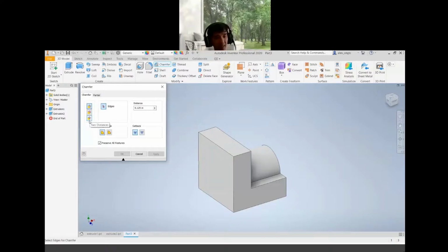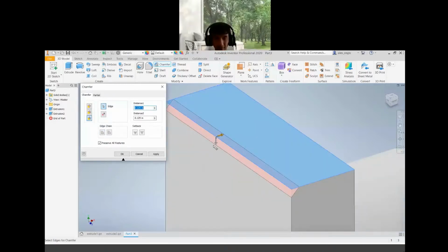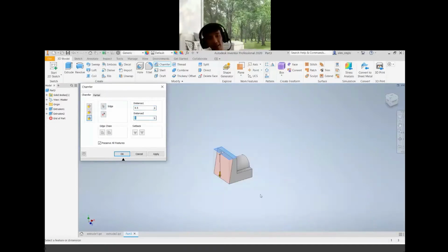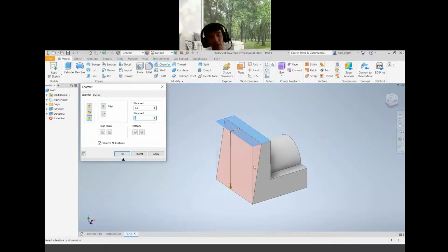Now they will ask you, status bar. Again, please refer to the status bar. Select center of circle. So it's very important for you to snap to the midpoint. So go to locate the midpoint. Do you see one green big dot? If like this, you don't click. Don't click until you reach here, more or less approximately at the midpoint of that line.